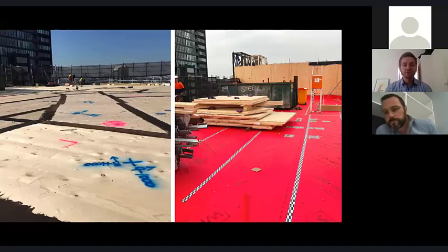Yeah, well, I think it's important to note that it's going to rain on site unless you've got a very small building. Chances are you're going to get some water, and it's more about the management, as Rob has mentioned. Like, timber can get wet. I guess for me as an engineer, the biggest challenge I see is the potential issue with axial shortening, because if you're increasing the moisture content, it means that you're going to have a greater difference between what's installed, and then once you've got a constant climate, once it's all locked up and in use, there's a greater differential between the moisture content during construction and in use.